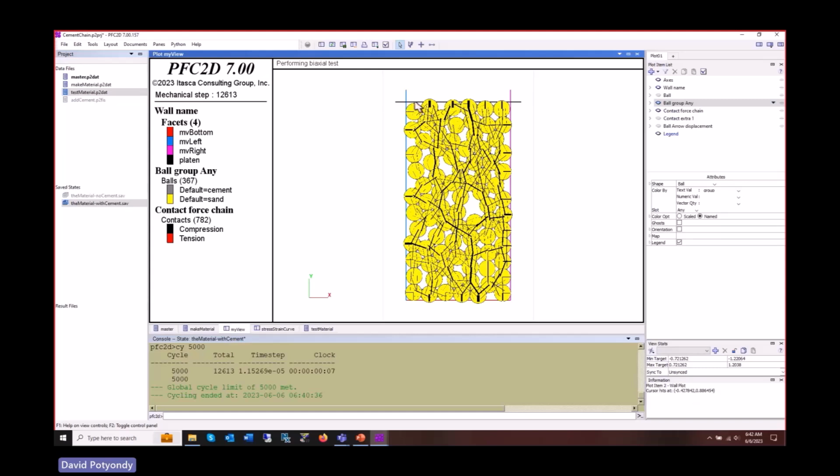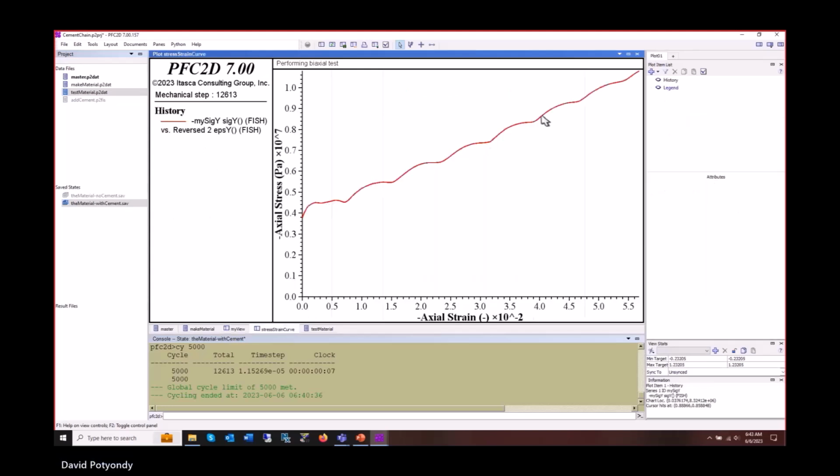It used to be 0, and suddenly it was 1e to the minus 2, which means that there was actually a compression wave that goes through here and bounces back, and that's causing a ringing in the system because of this compression wave. It's like moving down, and then it goes down a little bit, comes back, goes down, and it's a pretty minor thing, but that is happening.